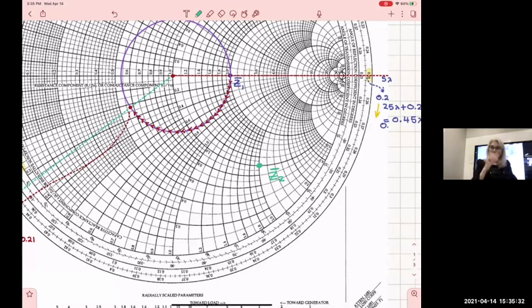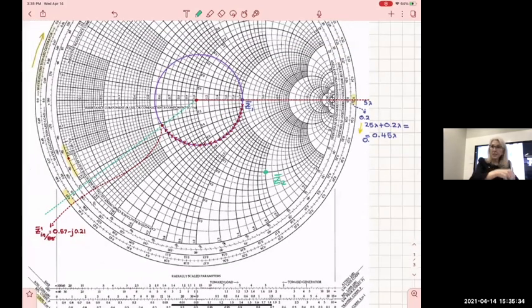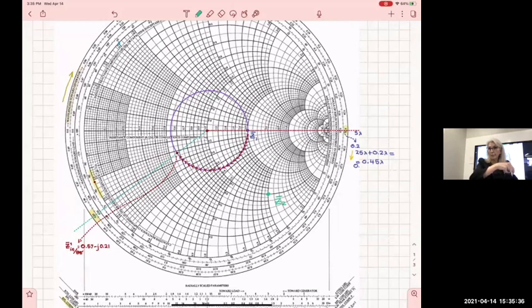Okay, now again, I'm going to write the circle of this section, transmission line, because these two transmission lines have different circles, all right? They're not the same. So the circle for the green point, which is like the transmission line that goes diagonally, is going to also have its center at the center of the Smith chart, and it's going to go through point Z2. So now I'm going to write a different circle, bigger one.